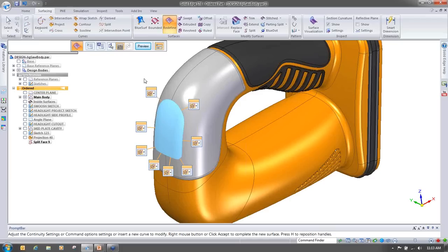Okay. Now let's hold the phone here for a minute. I want to point this out. This is one of the newer enhancements in ST6. We have a lot more control when it comes to our edge conditions and how we're handling our surfaces right at the actual surface. So the first thing I want to point out is we do have one single surface, because we went ahead and redefined those two segmented faces and made it a single surface. But notice how Solid Edge recognized everything as curvature continuous.